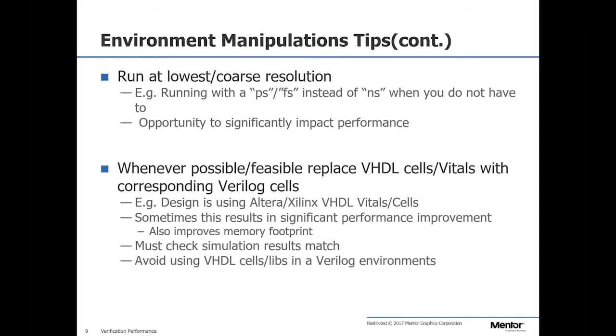So if you have a choice, even if you've done your design in VHDL and your test benches in VHDL, if you have a mixed language simulator and need to do a gate level simulation, create a Verilog netlist. It will work. There will be no issues, and it will be way faster than using VHDL VITAL cells.